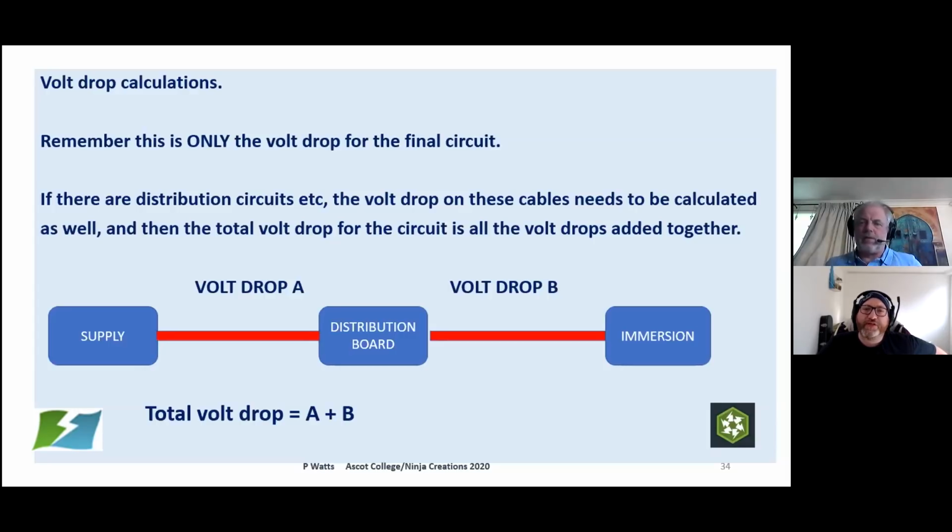All right. Are all copper cables the same? Can poor imported cables have higher resistances due to impurities in the copper? Yes. This comes back to the idea of getting reputable suppliers, really. Do you remember the training cable fiasco? There was a cheap rubbish cable which had a red stripe down it. It was cheap as chips, and it wasn't copper. It was a mixture of metals. You sneezed on it, it'd break. It was basically produced for training centres to give us high resistance values on small test rigs. But we weren't allowed to liven them up, which meant we couldn't do IR tests. So they only had one function, which was really to practice cable installation skills, but you couldn't really do much.